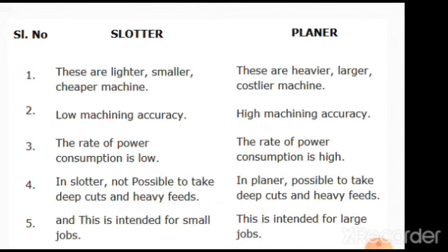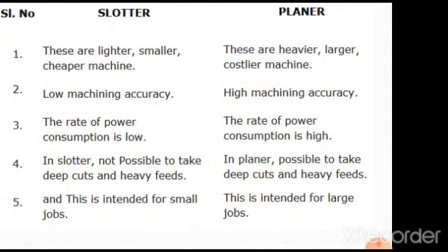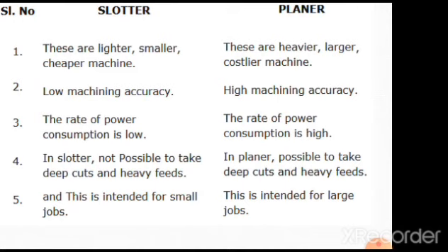But in the case of a planer it is possible to take deep cuts and heavy feeds, because the construction of the planer itself is such that it is a very big machine compared to the slotter. And the slotter is intended for small jobs. This is also very, very important, as I have told, because the size of the planer is minimum 3 to 4 times bigger than the size of a slotter.